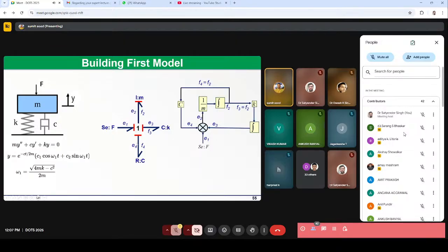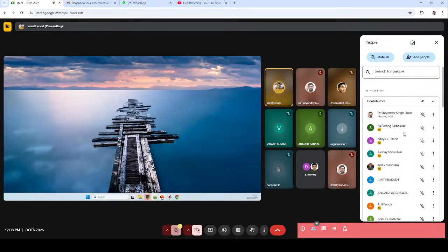You can use either specialized software to model this directly in the bond graph approach, or you can also use MATLAB Simulink, if you have it, in order to simulate this system. So just to quickly see how this can be simulated in different software, here is a small demonstration. To simulate this, we consider that the mass is 1 kg, the damping coefficient is 0.05, the spring coefficient is 20, and the force is 10 Newton. So just to quickly see,